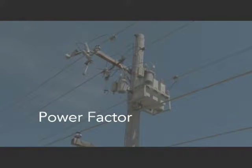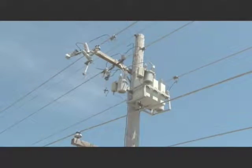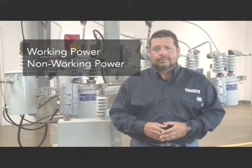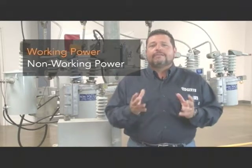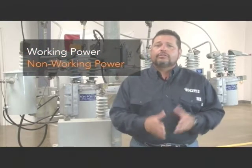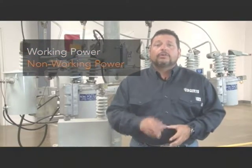Power factor is the ratio of useful working power in kilowatts compared to the total power in kilovolt amperes supplied to the circuit. Total power in a circuit is made up of two components, working power and non-working power. Working power is the power available to do work. Non-working power is often referred to as reactive power. There are two types of reactive power, inductive and capacitive.